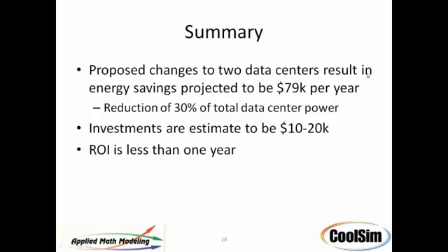DX-based units, the older ones, you can't put variable speed fans on because the evaporators will freeze. So in some cases you are constrained. It does depend on the situation. If whoever asked that question would like to contact me, we can take a look at their specific situation and talk about it or give you more detail.